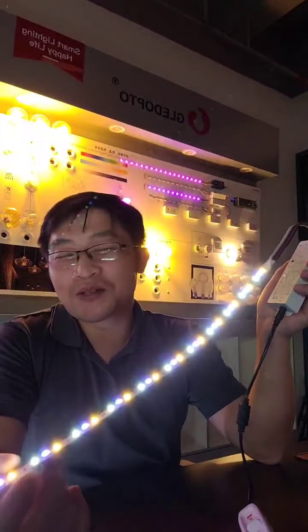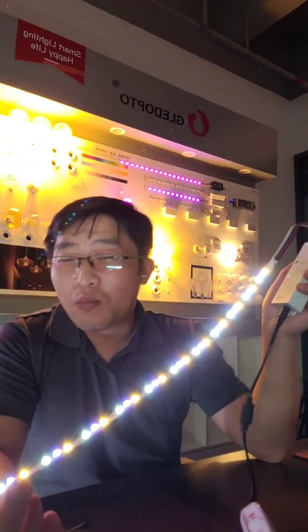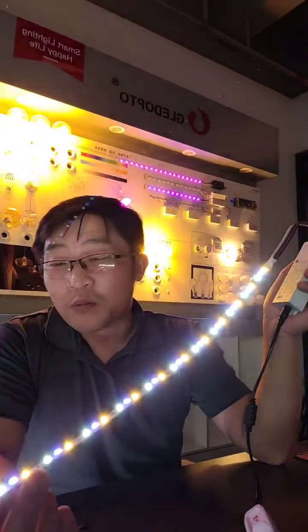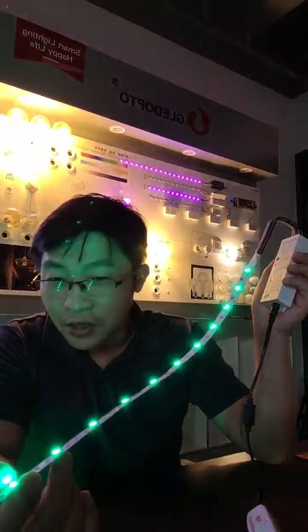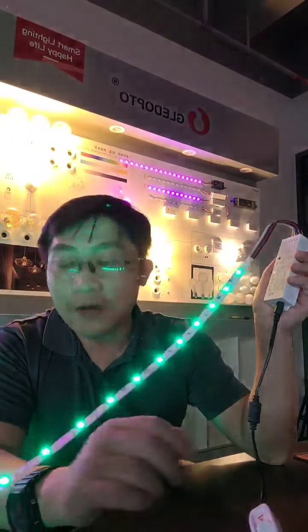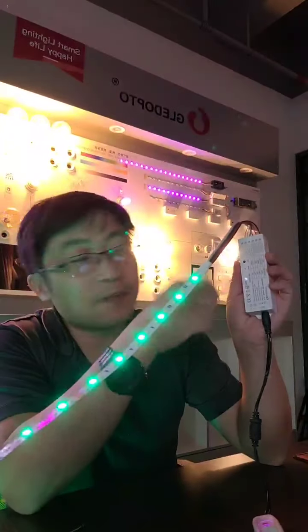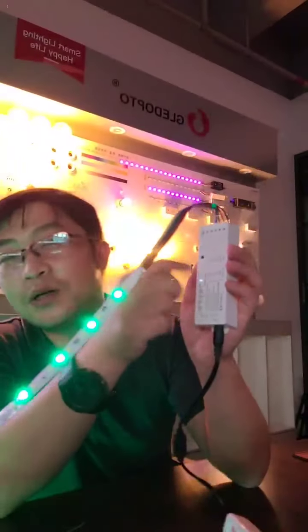Very easy to make a factory reset by pressing the reset key. If you know about Gledopto, we have been making ZigBee controllers for many years. Before, there was no reset key on our controller. So to do a factory reset, mostly you needed to power on and off 5 times. But now we have the reset key. You can factory reset directly by pressing the reset key.